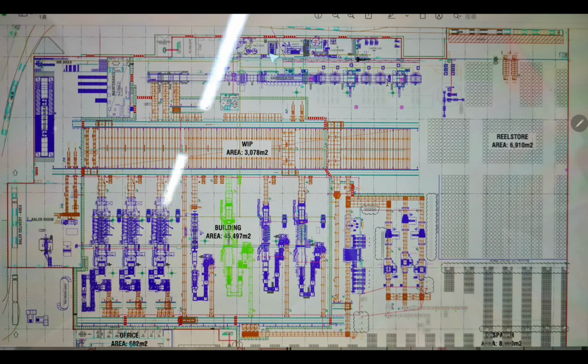So next is our boiler room. In the boiler room, you need to choose a very good, fuel efficient boiler. You choose an economizer. You try to get a low condensate and high condensate recovery system. If your power setup is running by generator, you try to buy an HRSG system to take the generator exhaust heat and run the HRSG to help the boiler.